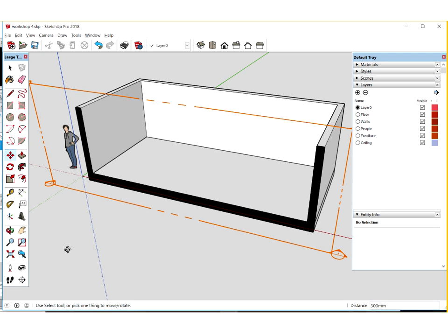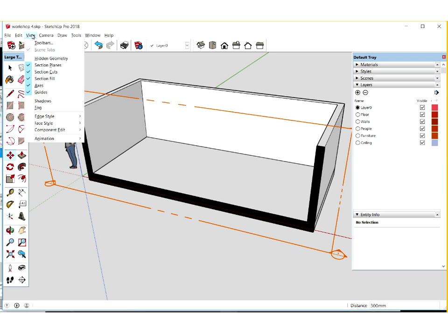Put up a green tick once you've finished to create a section. The visibility of sections we control through our view menu in SketchUp. It's always worth having a look in the view menu and seeing what's ticked or unticked. Okay, so when we're working with sections, we've got section planes and the actual cut itself.